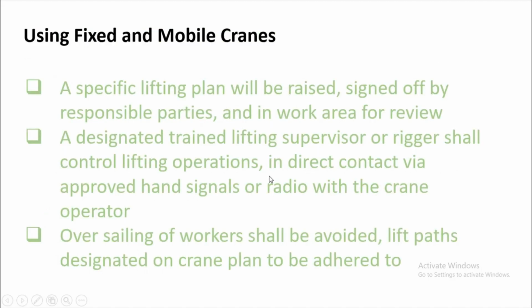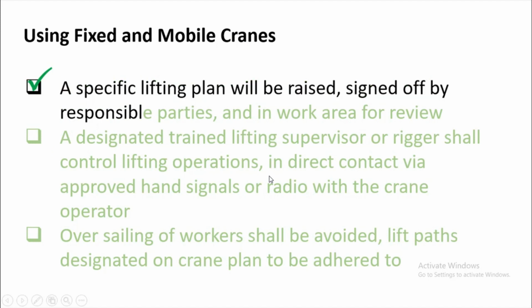Using fixed and mobile cranes, a specific lifting plan will be raised, signed off by responsible parties, and kept in the work area for review. So if you are using fixed or mobile cranes, they should have a specific lifting plan. And make sure that the lifting plan is signed by responsible persons, and make sure it is available in the area for the authorities' review or any concerned persons.